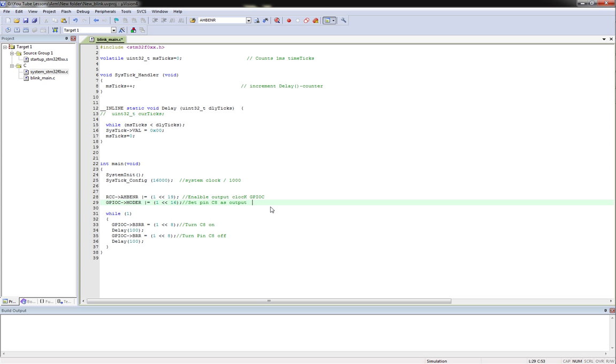Now this port and this pin by default is a digital GPIO port, so that's why I picked this one. So I don't really have to do any other defines to configure it specifically for what we're doing, but always keep track of it. Always watch your ports, especially those that have multiple functions on each pin, because you may have to set up special things.